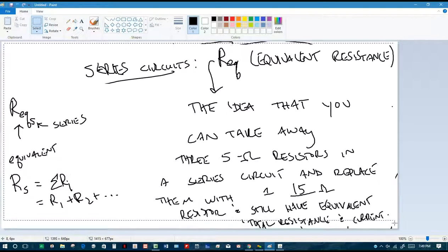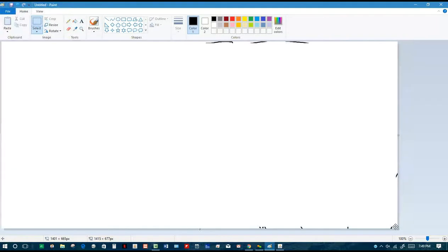the idea that all things have resistance, okay? Physically, there's nothing in our universe that we've found with exactly 0 resistance to electricity flowing through it. Everything has some resistance, but they all have different amounts of resistance. Things that are metals are conductors, they have low resistance. Things that are insulators like rubber, plastic, wood, styrofoam, those all have a very high resistance, right?